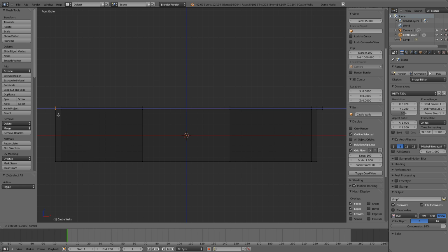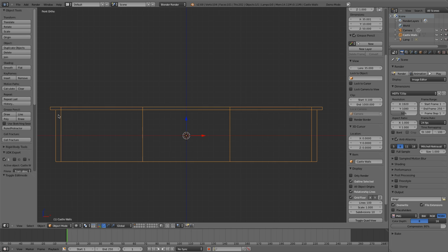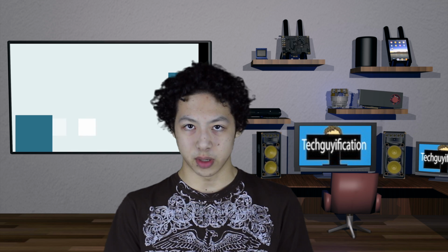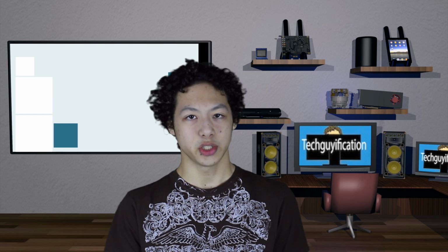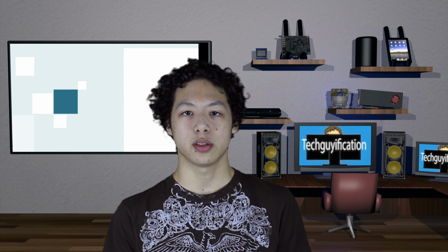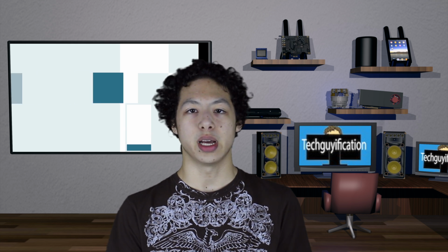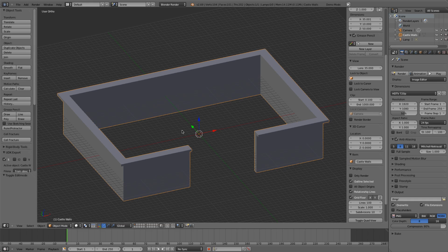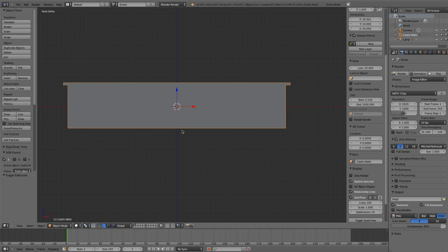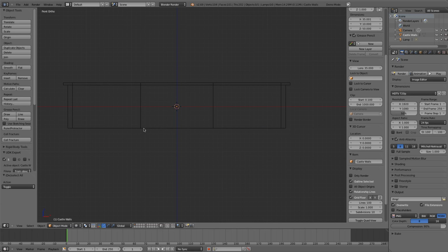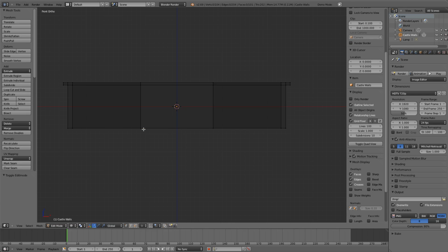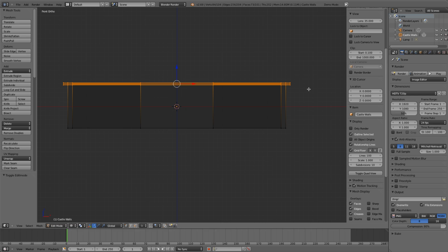So now deselect the vertices by pressing A, then Tab to go into object mode, then Z to enter solid shading mode, and now you can rotate your display to see what we've done three-dimensionally. So now go into front view by pressing numpad 1, then Tab into edit mode, then Z to enter wireframe mode, and then box select the entire 2 rows of vertices on the castle.